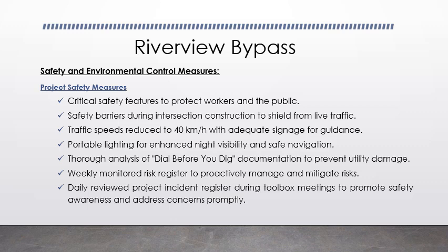And we'll do a thorough analysis of the Dial Before You Dig documentation to prevent utility damage. We'll also have some pothole investigation if we need. And we'll monitor the risk register weekly to proactively manage and mitigate any potential risk. And we'll review the incident report register on a daily basis just after the toolbox meeting, so that we can promote safety awareness and address concerns promptly.